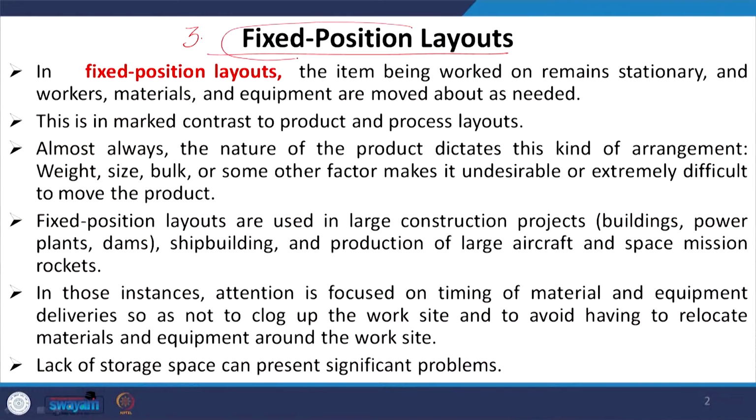But in the fixed position layout, here the job is stationary, that is the meaning of fixed position. The job is stationary while the tool is moving. The tool which is required to perform some kind of operation will go to the job and perform the operation, and then again go back to its original place. So, in this particular case the job is stationary while tools are moving, coming to that particular job, and then once they have done their work will go to some resting place. So, it is a very reverse kind of arrangement.